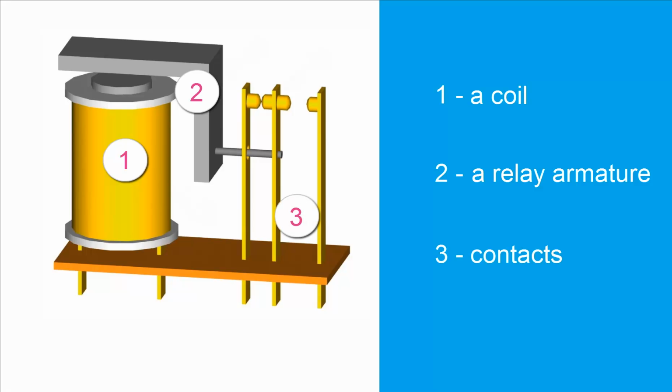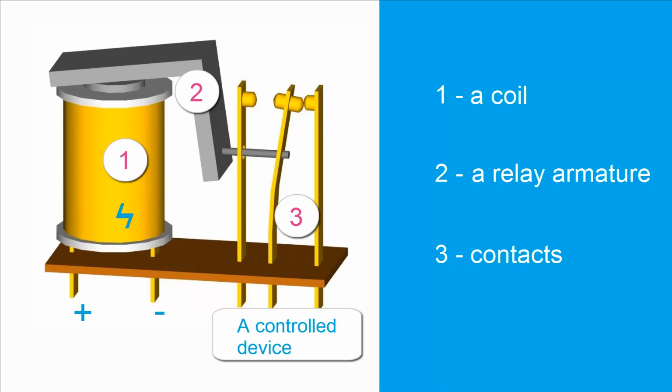When voltage is applied to the contacts, electric current generates a magnetic field that causes a travel of a ferromagnetic relay armature mechanically connected with contacts, and further travel of contacts commutates an external electric circuit.